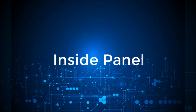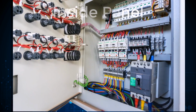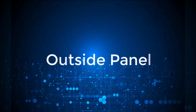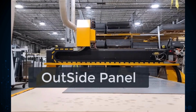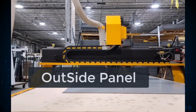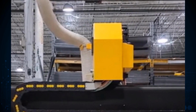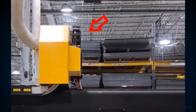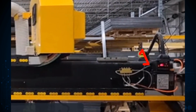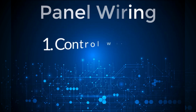Inside panel components: components installed inside the control panel include magnetic contactors, breakers, relays, timers, etc. Outside the panel components: equipment that is installed inside the machine rather than on the panel itself falls under outside the panel components. These components are electrically connected to the panel but are not physically attached to it. This includes motors, actuators, heaters, etc. Additionally, input sensors installed on the machine also fall under this category. When wiring these components, we divide the wiring into two sections: control wiring and power wiring.